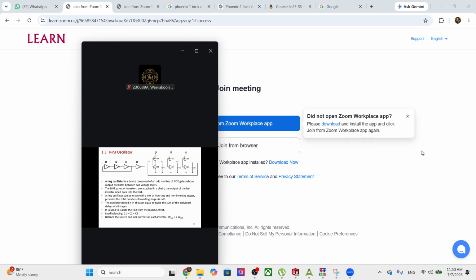We cannot take 4 because 4 is a stable circuit, right? Input becomes output. Our A beta is not equal to 1. But odd numbers of inverters, either 1, 3, 5, 7, 9, 11. You can go. You can come up with some idea. Or if you do not have an idea, you come and see me. I will tell you how to do that.